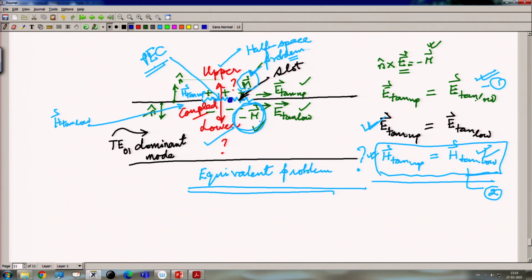Similarly, I would assume a point magnetic source located here, corresponding to this magnetic current minus M, and find out the radiated field inside the waveguide due to the unit impulse magnetic current resident on the lower surface of the conductor. Therefore, my complete attention shifts from the amplitude of the magnetic current source to the boundary condition of the problem. This is the heart of the Green's function.